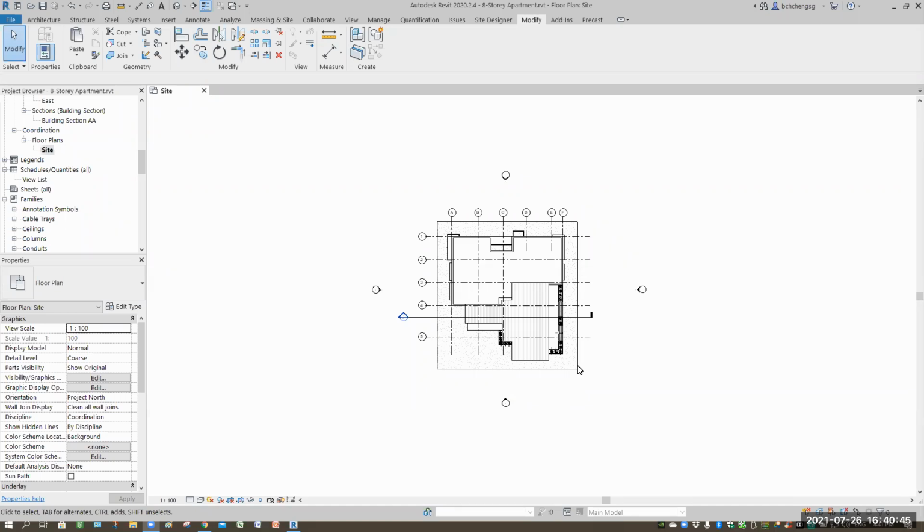So BCA did say that in future, if you are doing a BIM project, you should request from the surveyor to provide the topo points with X, Y, Z. Height is important. Not just X and Y correct, with only the marker value for Z correct while the point is still 2D.